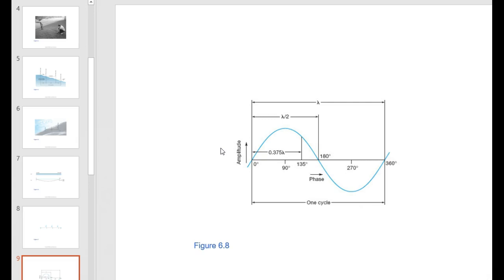Now, once in a great while on the total station, you will get 2 possible readings, and it will give you 2 numbers. It might say 26.41, comma, 267.42, or something like that. When it does that, it means your total station has found 2 mathematical solutions that are equally possible mathematically.